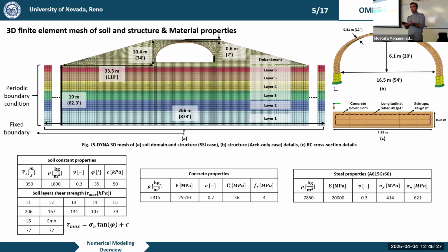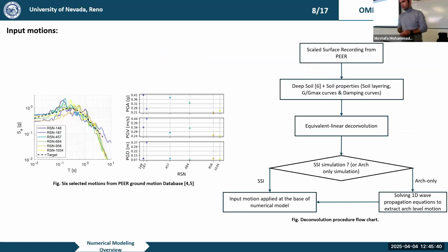But I don't know if we amplify the input motions whether it will still make sense, or whether we need to think about something else. Also, since you mentioned it, if you go back to our ground motions, you see there's significant scatter, especially in the PGA over PGV ratio. That is an indication of the frequency content, and maybe sometimes the existence of a pulse in the ground motion. Those will start becoming important when it comes to modeling those little nonlinearities that may take place.